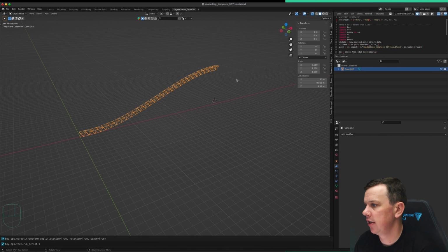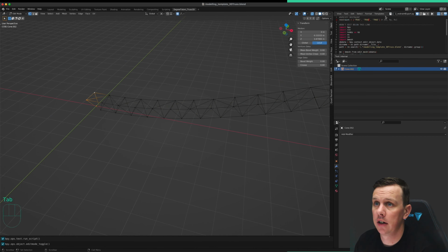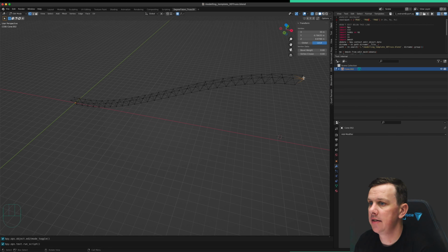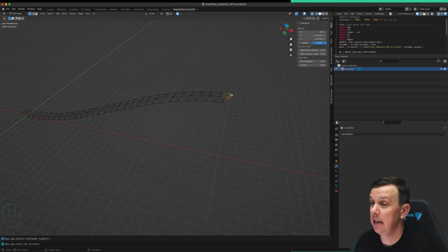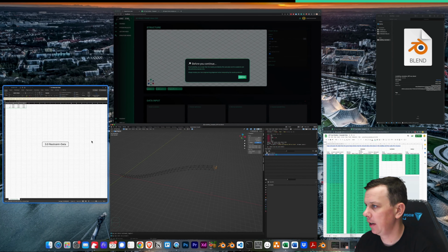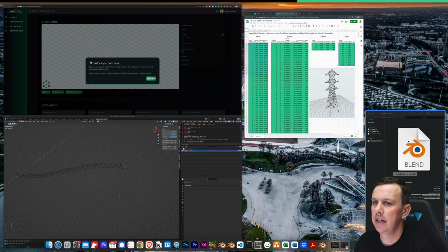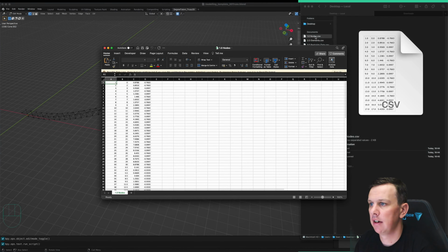Let's go to file number 2. Right, let's just imagine that this thing is, tab into edit mode, select that guy and that guy, true, true, true. So that's going to be a pin and a pin. That's fine. And I want these two to be just restrained. I want them to be free in the X direction, right? So that means I want that to say false. And now I can run. I can't run it yet because if I run it now, it'll override what's there already. So let's just bring the data into our solver as we generate it.